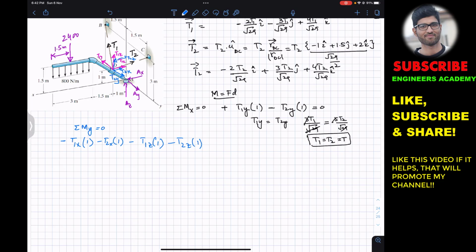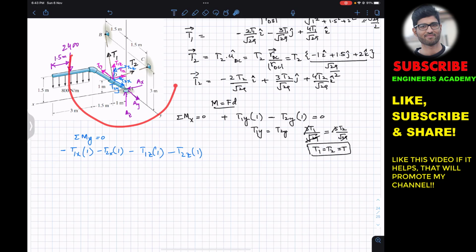Then this 2400 resultant is going to produce a counterclockwise moment about the y-axis. If we curl our right hand fingers in this direction, the thumb will point out in the positive y. So we will have plus 2400, and the perpendicular distance of this 2400 from the y-axis is 1 plus 1.5 plus 1.5, which is 4. So we will multiply this with 4, and this is equal to 0.